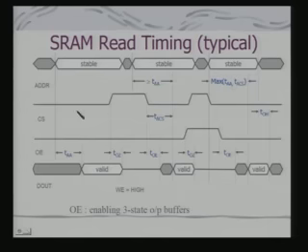So what you have got here is the address which is shown here as a basic stable part, and here we are showing the data which is coming out as a valid data, because I am now looking at primarily the read timing, okay. And this output enable, so when there is output enable low, you actually are getting the valid data.